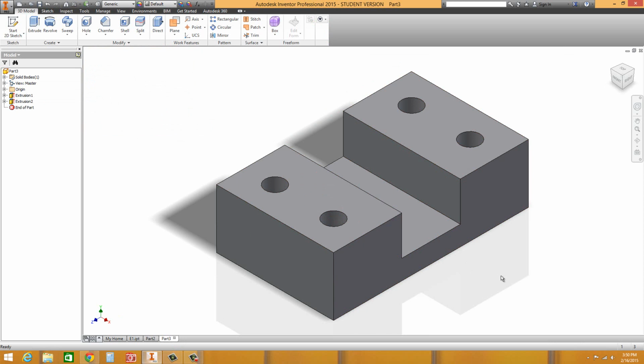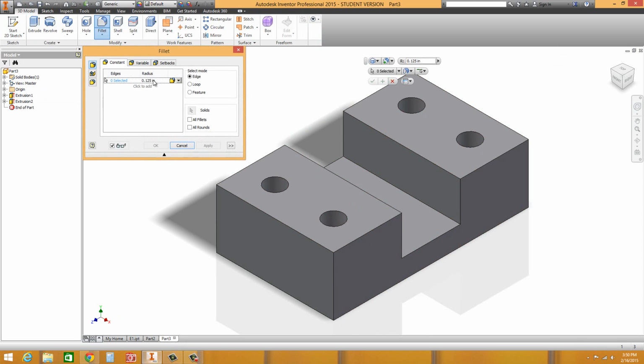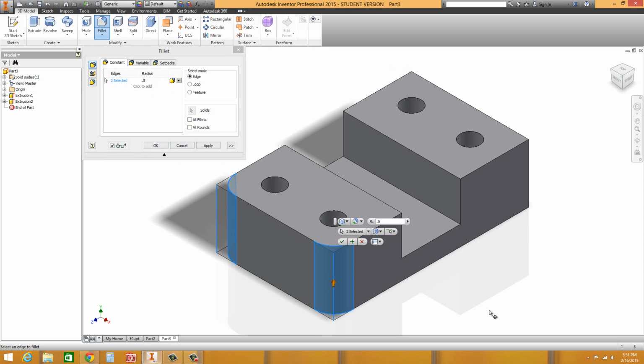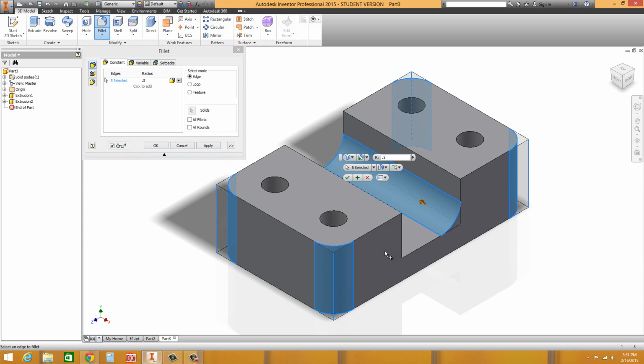All right, that completes that exercise, or that lab. That's lab 1B. But I'm going to show you a few more things. Have a little fun with this. Underneath chamfer, hit the little arrow and go to fillet and set the rounds maybe to 0.5. And select these 4 corners. You could select these corners too, or these inside edges. Hit OK.